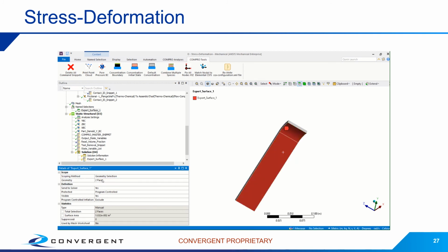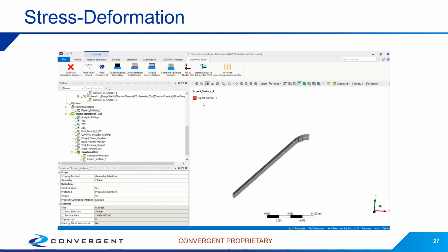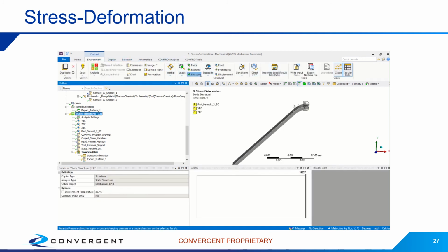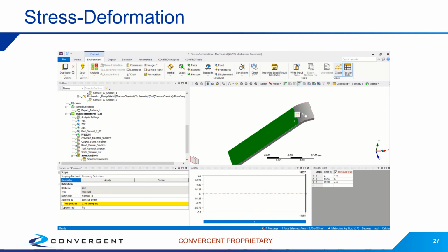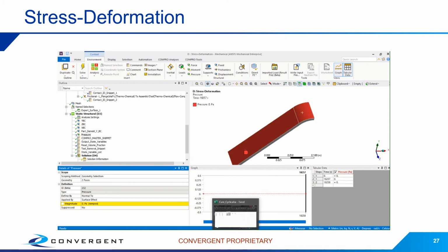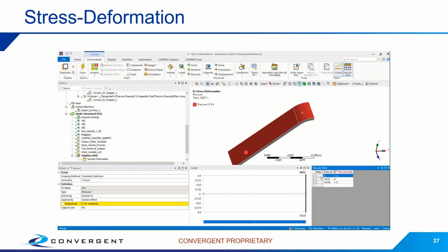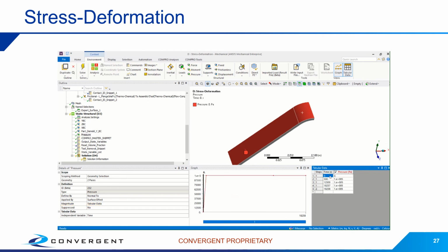Perfect. So the next thing that I have to do is apply my consolidation pressure, of course. And again, I'm going to go up to my handy Excel notebook, paste those in here. And of course, during demolding, we've debagged this, so I want to deactivate the applied pressure. I don't want any applied pressure in that step.